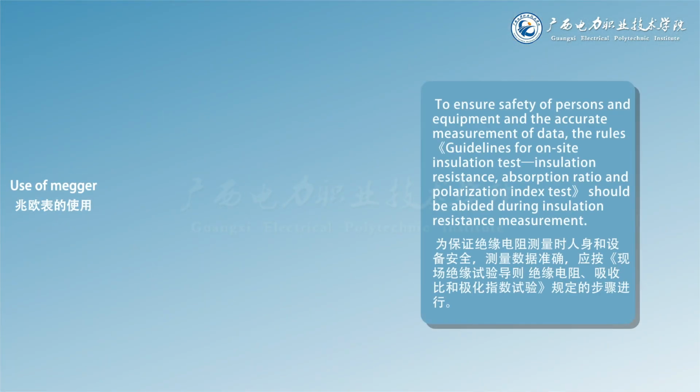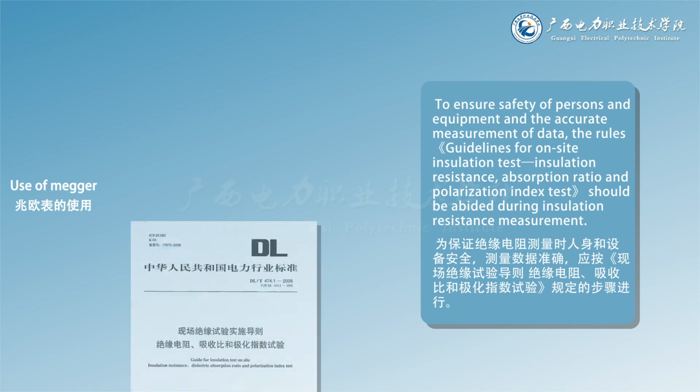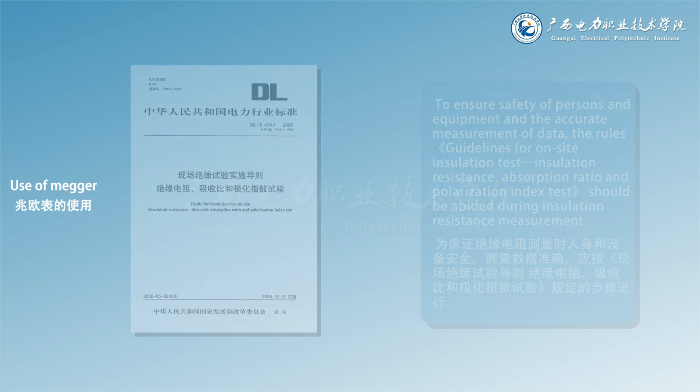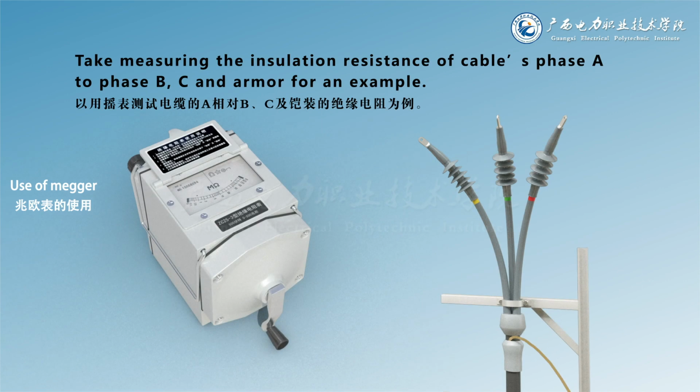To ensure safety of persons and equipment and the accurate measurement of data, the rules and guidelines for on-site insulation test, insulation resistance, absorption ratio and polarization index test should be abided by during insulation resistance measurement. Take measuring the insulation resistance of cables phase A to phase B, C and armor as an example.